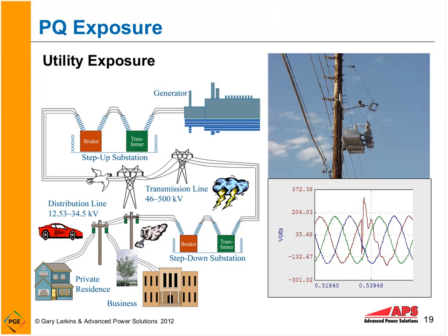We have exposure, and you can see here I have a little graphic of a raptor. When I worked for one organization, we had raptors building nests up in the 345 kV line, which when it faulted across the insulator, when they got contamination on the insulator, it would bring the whole grid voltage down in the valley. You have lightning that can strike, whether it be a substation or power lines. You have windstorms, tree limbs, car hits pole. These are all things that can contribute to power anomalies on the power grid system. And these are a natural operation that can occur because we have exposure out there.